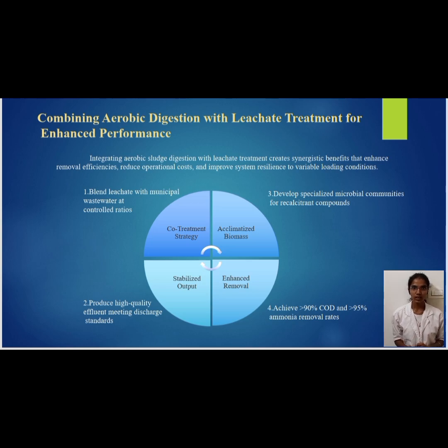In this slide, why combine leachate treatment with aerobic digestion? Mixing the leachate with regular wastewater can help microbes adapt better. Second, removal of pollution improves. It saves a lot of money and allows sharing equipment cost. General rule: only 5 to 15% leachate should be mixed at first.